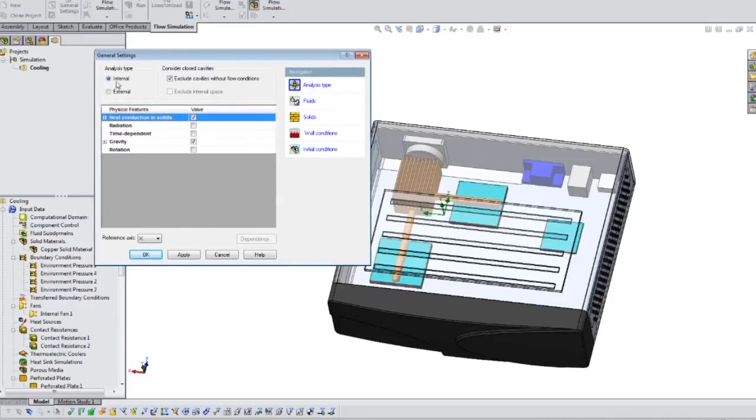Again, going back to our analogy about existing equations, we can solve for the flow inside of a pipe pretty easily. But as soon as you start adding bends or multiple branches, those equations start to get pretty complicated. So tools like SolidWorks Flow Simulation solve the Navier-Stokes equations to really understand what the fluid flow is inside of a complicated system that isn't easy to calculate by hand. And being a general purpose CFD tool means that it can do a little bit of everything.